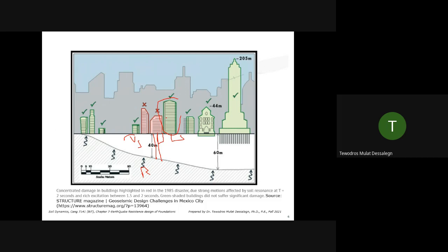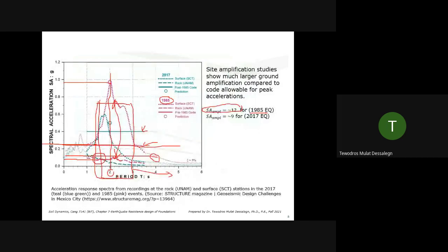Or you should recommend very tall buildings, or shift the period somehow. Do not stay within this range. If you have to stay, what should you do? You should design it properly, right? You should be able to resist, maybe with more reinforcement, so that beams and columns don't crack and fail. So this is a very critical step at the initiation of the project, and it's mainly dependent on geotechnical engineers.